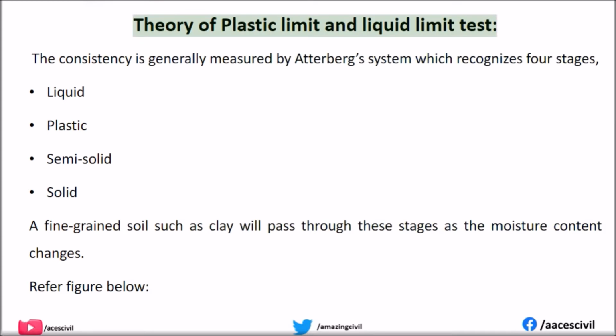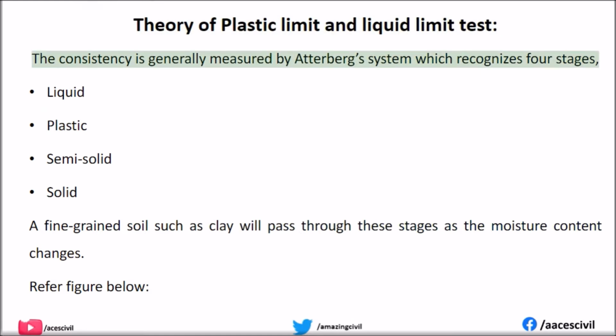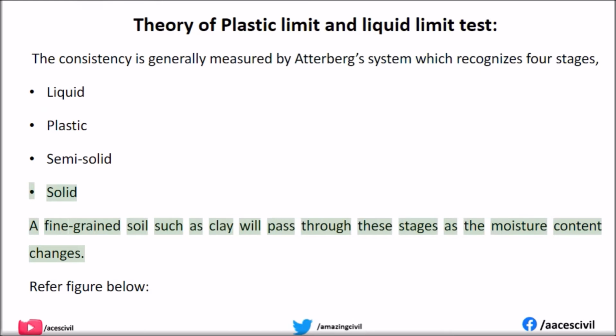Theory of plastic limit and liquid limit test. The consistency is generally measured by the Atterberg system, which recognizes 4 stages: liquid, plastic, semi-solid, solid. A fine-grained soil such as clay will pass through these stages as the moisture content changes. Refer to the figure below.